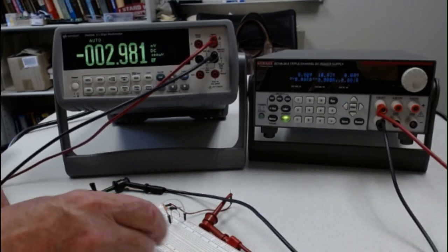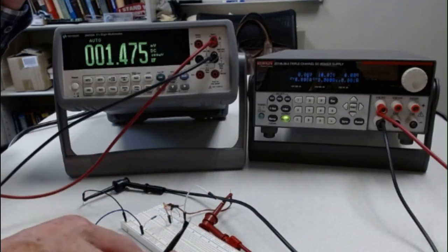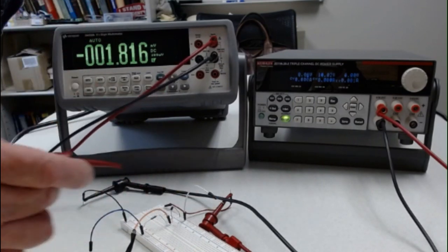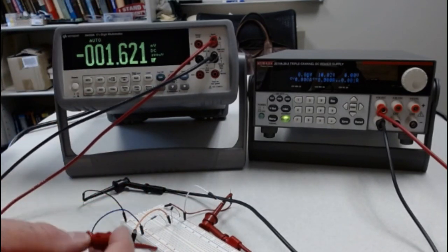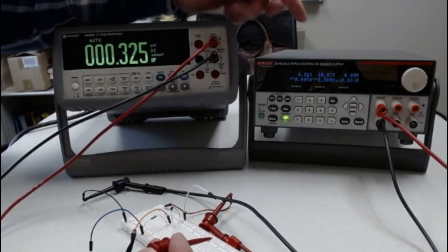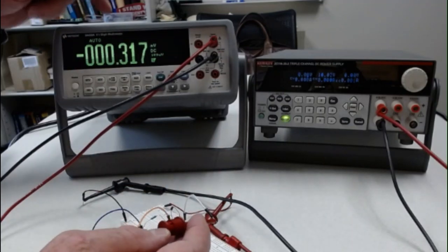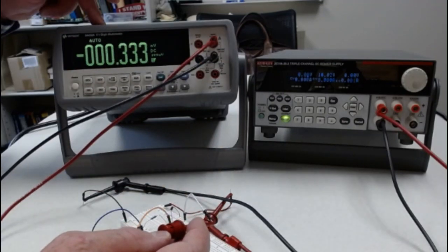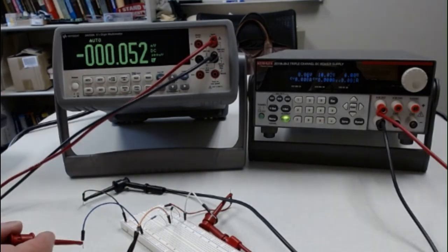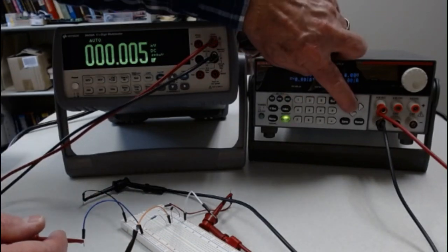Because we're going to see that it's going to be pretty similar the whole way through. So again, we're going to hook up the black to the middle, and we're going to basically just go between the two with the red, but again, ignore the minus sign. So we're now at 0 volts, and we're going to measure the diode here and the resistor here. Okay, we're going to go to 1 volt, 1, enter.